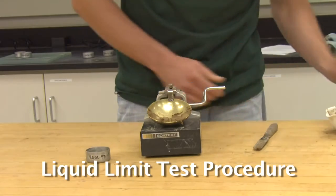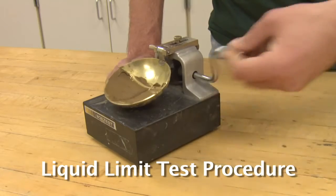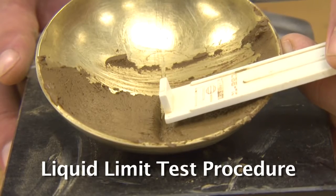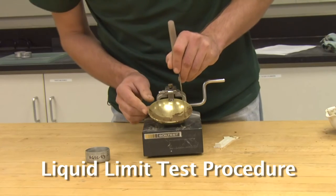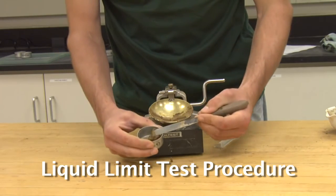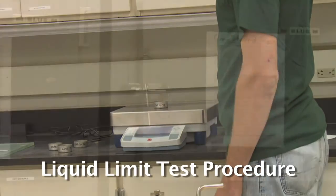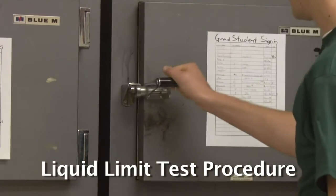Once the groove has been made, rotate the handle at 120 revolutions per minute, 2 cycles per second, and count the number of blows it takes to close the groove in the soil pat 13 millimeters or 1/2 inch, which is the width of the grooving tool handle. If the number of blows falls between 15 and 20, scoop out some of the soil and place it in one of the pre-weighed tare cans and record the new weight for moisture content determination. Place the can with the soil in the oven and reweigh it again in 24 hours.